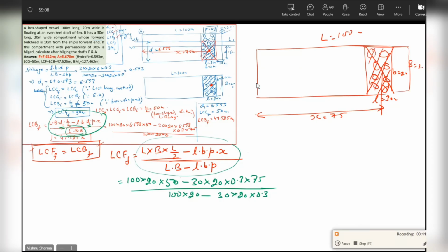In the bilge condition, is the water plane area same from keel to waterline W1 L1? Is it same? Yes, sir. In other words, if you were to calculate KB in this question, would you take it D1 by 2? Yes or no? Yes, sir. If the answer is yes, then LCB and LCF will be the same. Okay, guys? Fourth thing obtained.